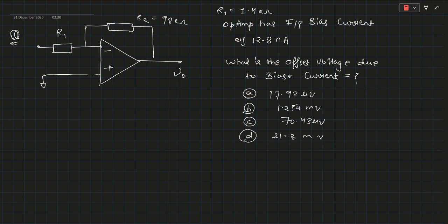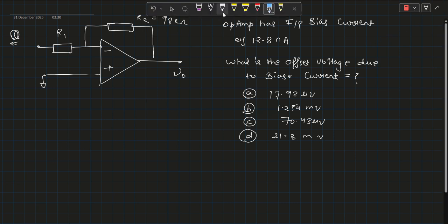In a real system, an op-amp is not an ideal op-amp. A non-ideal op-amp has some non-idealities, which result in some error voltage, an offset voltage at the output node when there is no input. There are two kinds of non-idealities, the first of which is offset voltage. It means there is an offset voltage at one of the inputs of the op-amp when there is no input voltage. I will explain on the paper.